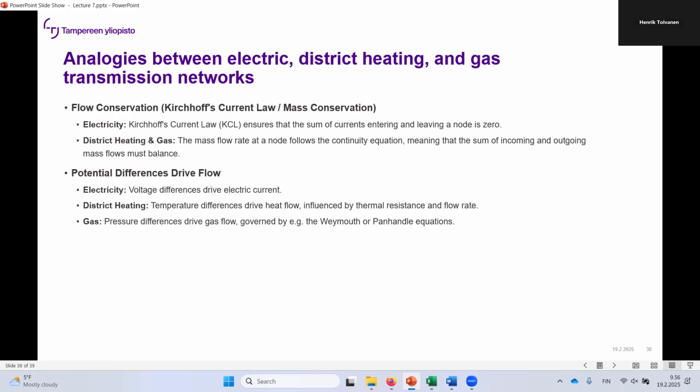But also the power flow is directly proportional to the heating value of the gas that's being utilized. So hydrogen versus natural gas: hydrogen actually has much less density. So for the same volume flow, you have less energy with hydrogen, even though with the same mass flow you would have more.